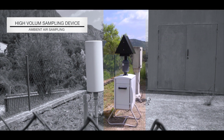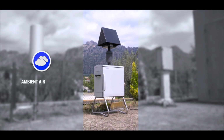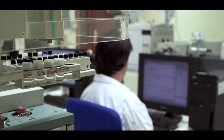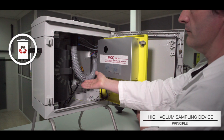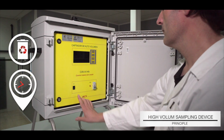To this end, it will be necessary to use an active high-volume sampling device, which allows collecting an amount of air sample enough to reach the limits of detection that the most modern instrumental techniques can provide. The basic principle of a high-volume sampling device consists in the collection of ambient air with the help of a pump during a period of time that can vary from 1 to several days.